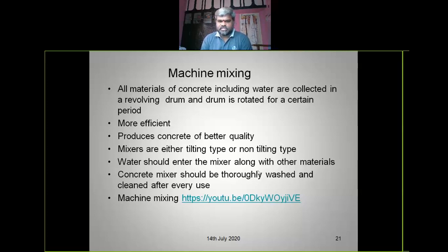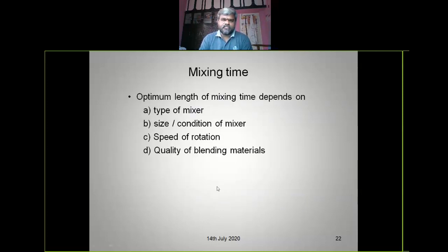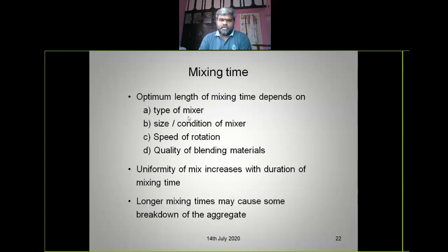Water should enter the mixer along with the other materials. The concrete mixer should be thoroughly washed and cleaned after every use, right? So the optimum length of mixing time depends on the type of mixer, size of the drum, speed of rotation, and quality of blending materials.